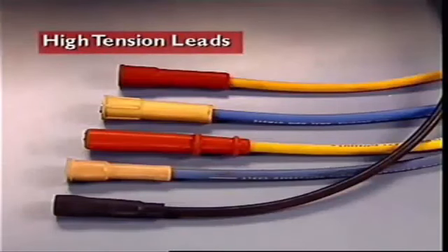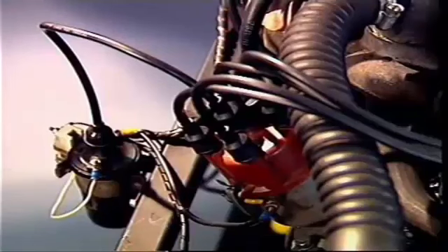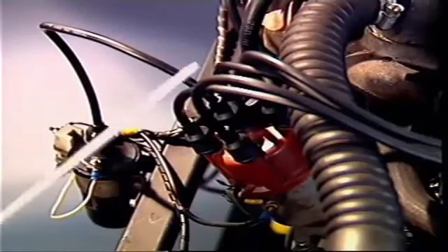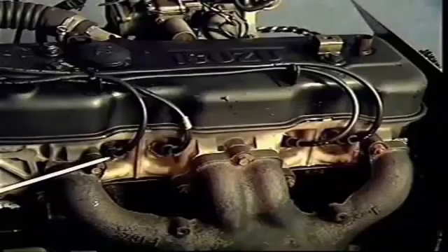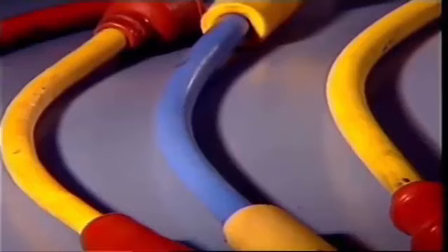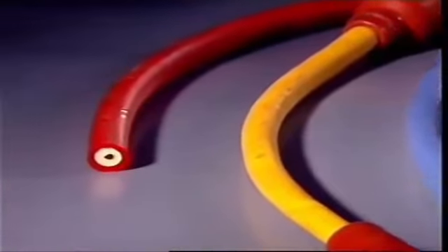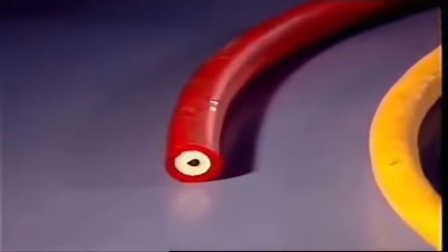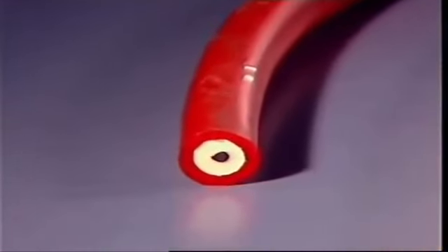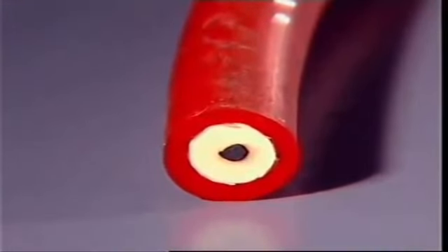The high-tension cables conduct the high output voltage generated in the secondary ignition circuit when each ignition pulse occurs. They link the high-tension terminal of the ignition coil, the distributor cap and spark plugs. Because of the high voltage, the cables are large in diameter and are made from thick-walled insulating material around a central conducting core. The heavy insulation prevents leakage occurring and also withstands the effects of high temperature, oil and moisture.